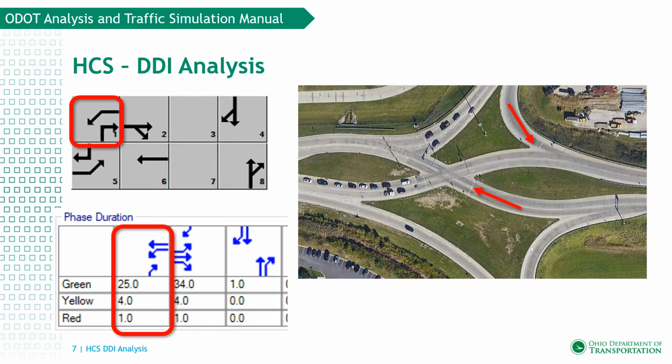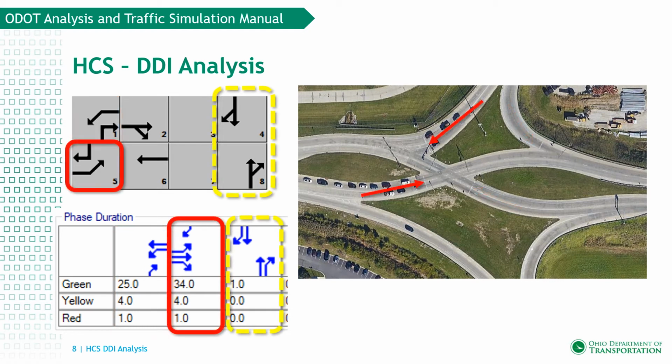First, the southbound left turn from the off-ramp, which has now been coded as a northbound right turn, goes at the same time as the westbound through movement. The eastbound left turn phase has been coded as a lagging movement. This allows the eastbound direction and the westbound direction on the major street to be coded as a split phase.